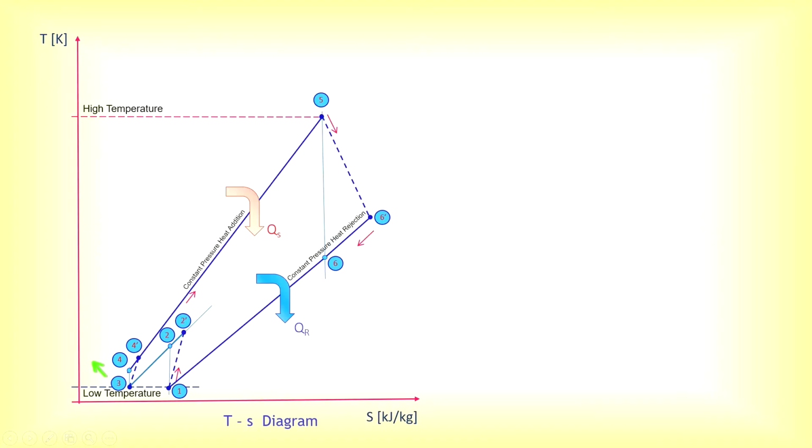So this is the TS diagram. Now, when you look into the TS diagram, you have one constant pressure line, two constant pressure lines, and the third one. So this would be the inlet, air inlet, okay, and it undergoes an isentropic compression in the first compressor, and this is due to irreversibilities.